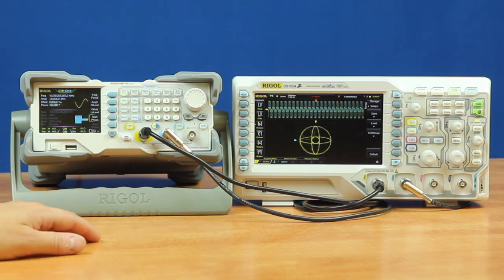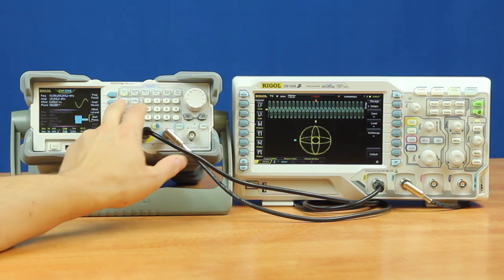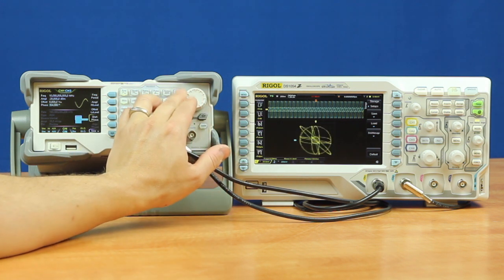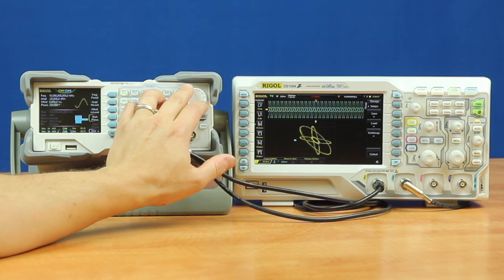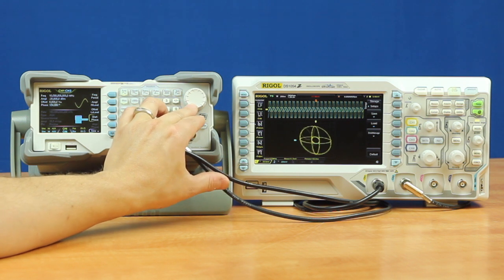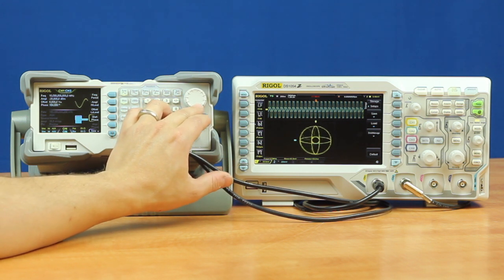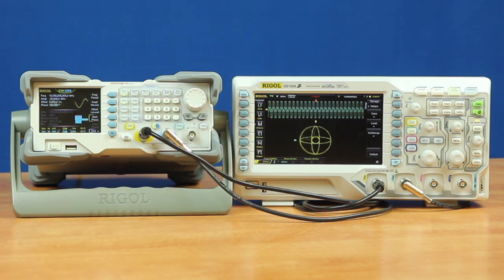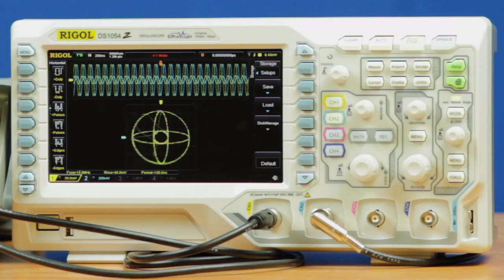to finalize this setup, you need to adjust the start phase by going to the sine menu, start phase on channel 1, and here we can adjust the start phase. The phase will not align directly because both channels are amplitude modulated, so you have to change the start phase until you get a nice round figure on the scope. And so let's look at about what this represents.